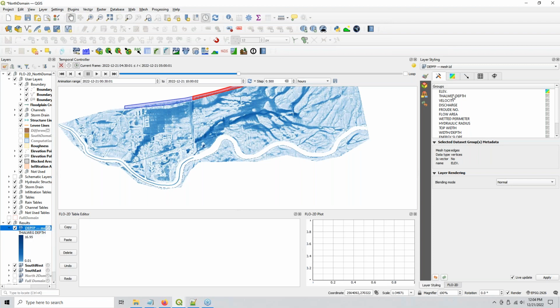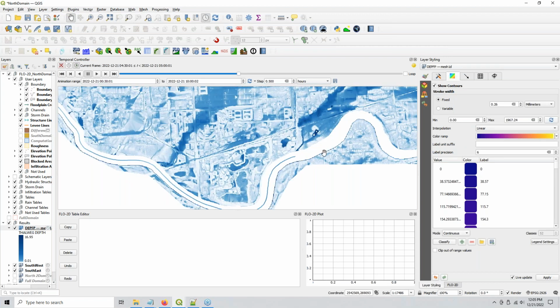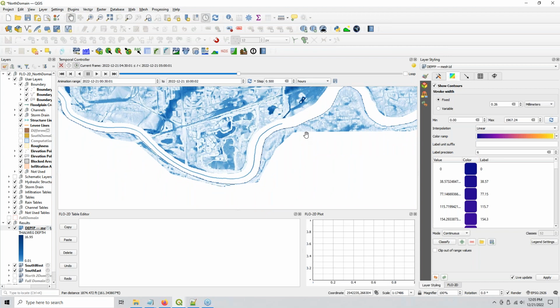So if you put in a 1D layer over here, you get water surface elevation, depth, velocity, discharge, limiting, or not limiting Froude, excuse me, this is not limiting Froude, this is calculated Froude, flow area, wetted perimeter. Everything that's in HYCHAN.OUT is in this, and you can map it. Although most of this stuff you don't really map. But the deal is that it's kind of funny because it's just a dot. It's just a line. It's not like a true channel.